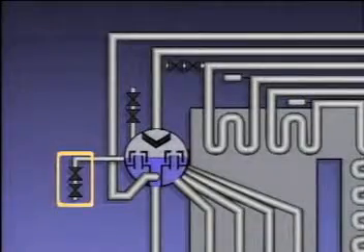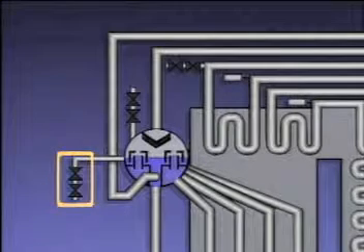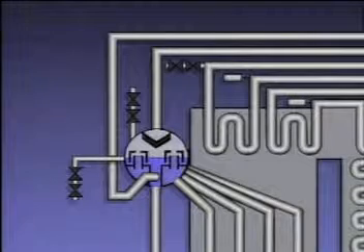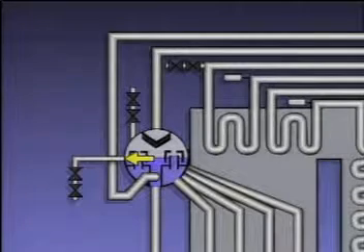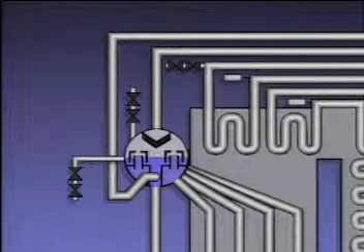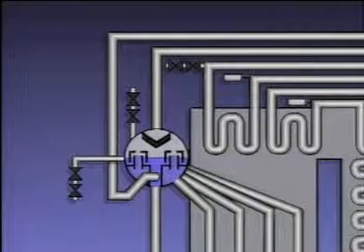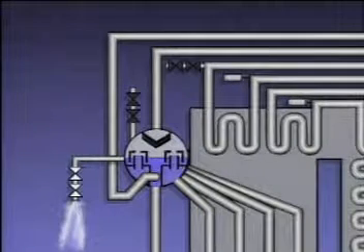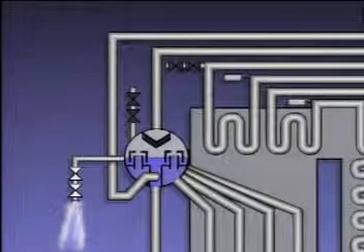Blowdown valves are a kind of drain that may be opened during boiler operation. One common type of blowdown valve on a boiler is a surface blowdown valve, which is located near the normal water level in the boiler drum. Contaminants commonly collect on the surface of the water in the drum. The surface blowdown valve can be opened periodically to remove or blow out water containing these contaminants.